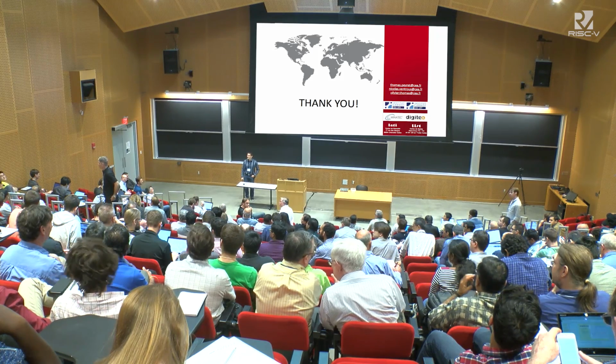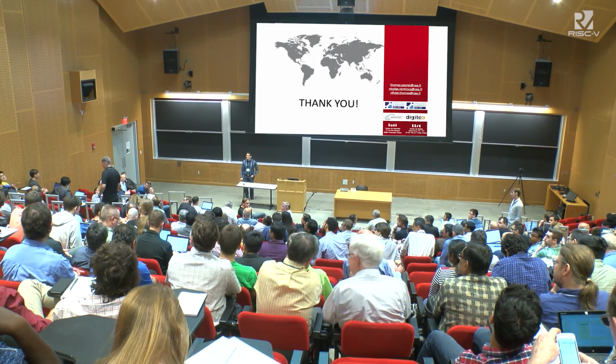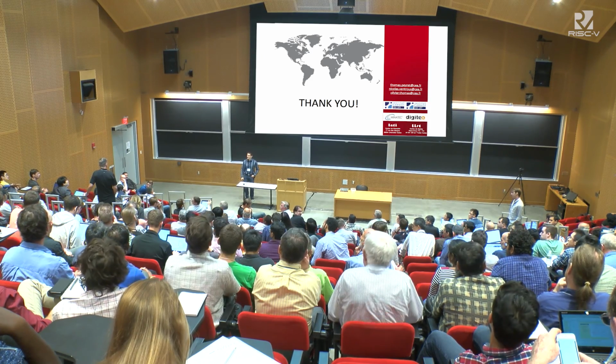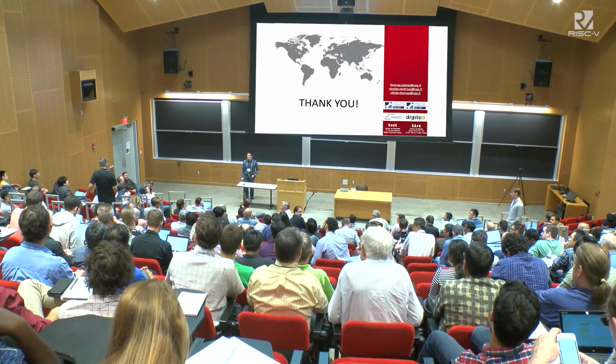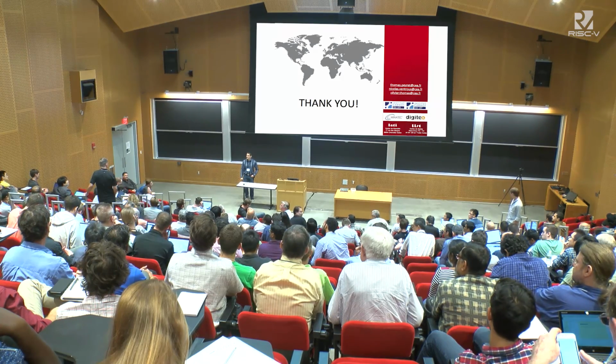Hi, Vijay Subramaniam from Microsemi. You had about 10 milliwatts of leakage power in your implementation. Did you use power islands or state retention, or was the circuitry active all the time?